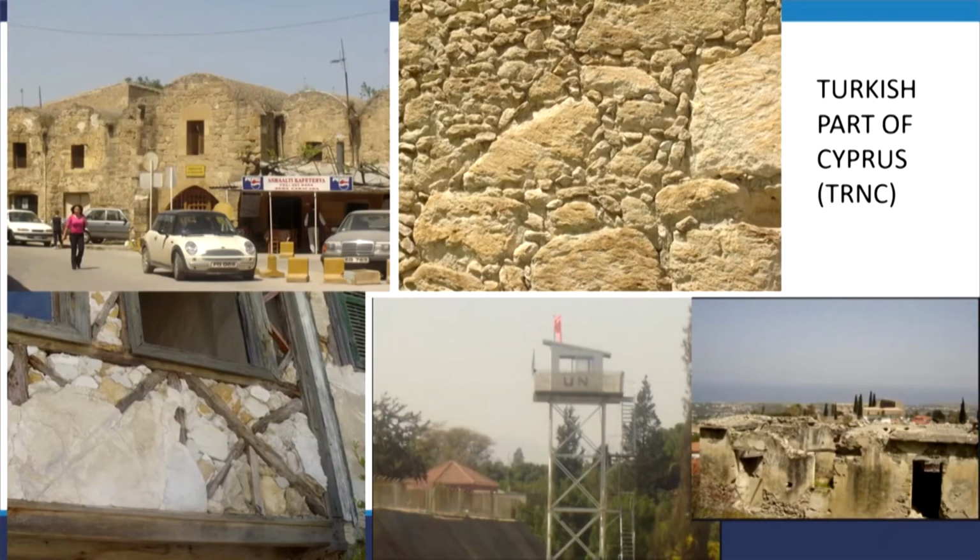The same is true of the Turkish part of Cyprus, the TRNC, in Lefkosa, where you can see, in Girne, many of these buildings built with stone. And here you can see the galleting techniques also. And of course, it is very relevant even in Himachal Pradesh, where you have the Dhajji Dewari constructions. It is built within a wooden frame, and the stone is composed within that.